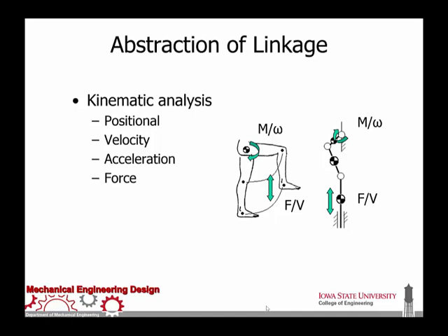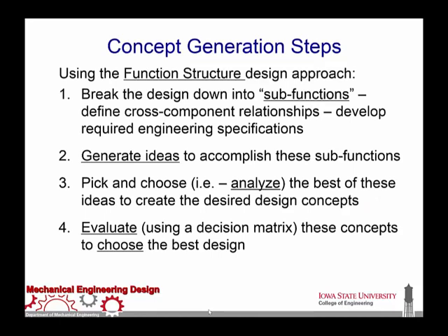Key thing about kinematic analysis is we're usually looking at positions and velocities, and oftentimes acceleration and force. These are all critical when determining forces and stresses and powers that could be generated by a system. So our concept generation steps, what we're looking at here and doing the math modeling is first we want to, using the function structure design approach, define or break our system down into sub-functions, define cross-component relationships. From there, develop the required engineering specifications.